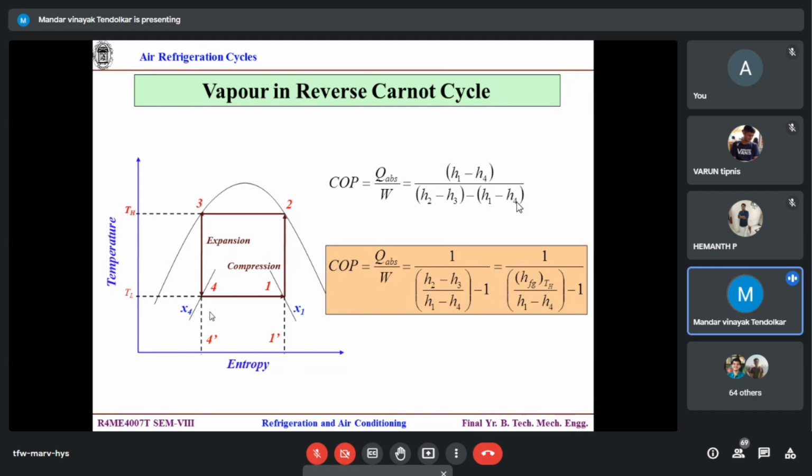The main point to be emphasized is not about the irreversibilities, but that when you try to execute the same process for gases, it is practically highly impossible because you have only one motor. In the piston cylinder arrangement, half of the cycle you want to move with infinitesimally slow speed, and the remaining half infinitely fast. Two reversible adiabatic means two isentropic and two isothermal. That is impossible. Here you get rid of that one part, half of the cycle. You need only one motor to run for only the compression and expansion process.